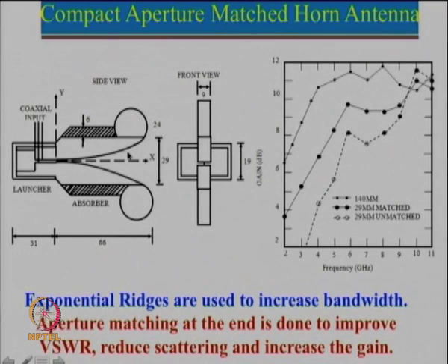So what happens is that the current which is coming over here starts rolling around this, so there is no edge diffraction taking place, and then this current here rolls around, and this one here actually is a microwave absorbing material. So whatever rolls around here gets absorbed here. So what is the reflected value? Close to 0, so nothing gets reflected back.